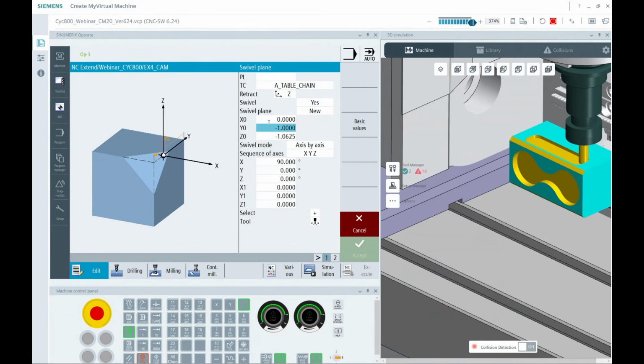Had I not had this shift in place, then as the operator, I'd have to think, okay, what's the thickness of this block? Okay, well, I know it's 1 inch. And then what is the depth of my pocket? Okay, minus 1/8 of an inch. So I should expect to see .875 here, plus or minus, right? So you have to think a little bit more.